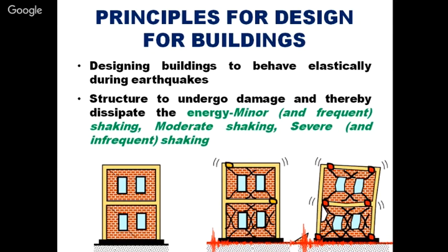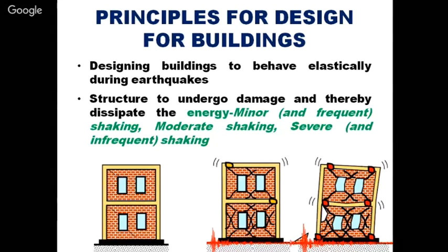Dampers are damping the earthquake forces, meaning they are resisting the movement of earthquake forces and the movement of the building because of that damping effect. Like in your cars, you have shock absorbers. Like that, if you connect your building with those dampers, it will behave like shock absorbing equipment, and your building will be safe during earthquakes.